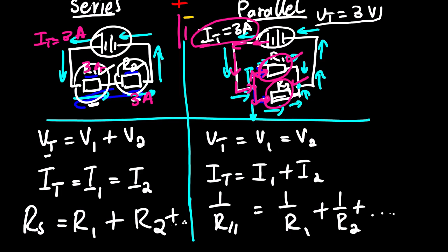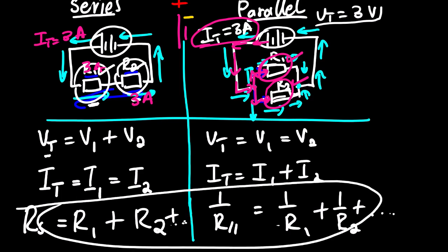Now to calculate the resistance in parallel connection, we are going to take the fraction 1 over the value of the resistance plus 1 over the value of the resistance. Now in this lesson video, we are going to close it up with the calculation of resistance, and then looking at lesson 102, we are going to look at another physical quantity. It might be the potential difference or the current. Now let us look at examples on how to apply these equations.